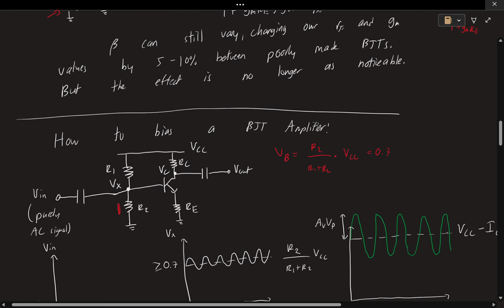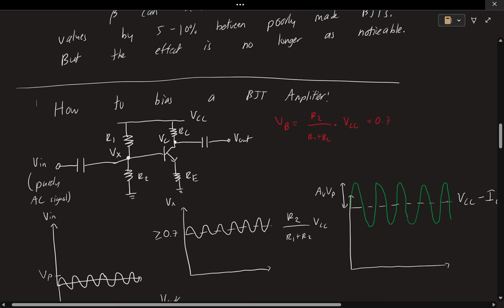Now the next thing you'll see here is we have a capacitor here, okay? So one thing to note is, typically when we make amplifier stages, when we make amplifiers in analog and RF design, we typically have several stages cascaded together. You string them together just like maybe in 102 you've talked about transfer functions, having different systems following each other. Same idea, okay? At least in RAP, we consider 1 megahertz waves from our MCU, scaling it up to 5 megahertz, scaling it up again to 27, sending it out to an antenna, right?